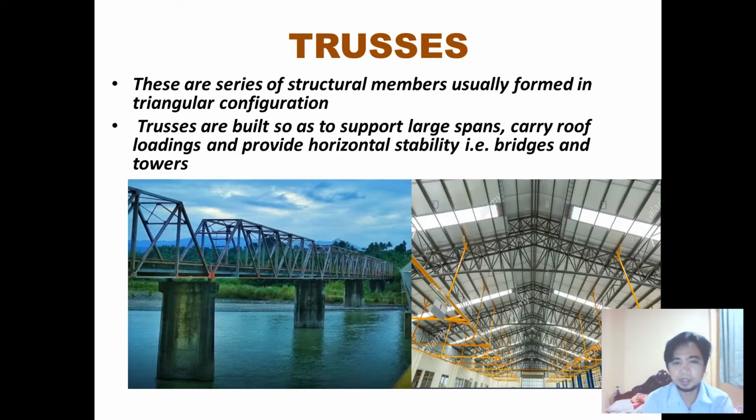At the same time, it carries the horizontal forces. Okay, so the effect is shear and bending. Unlike in the trusses, it would only become either tension or compression, or actually axially loaded. So take note of that. So truss loading is only axial, but less on bending.